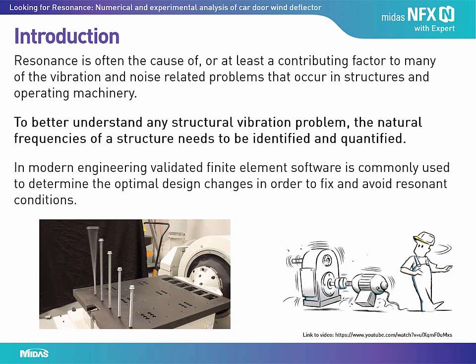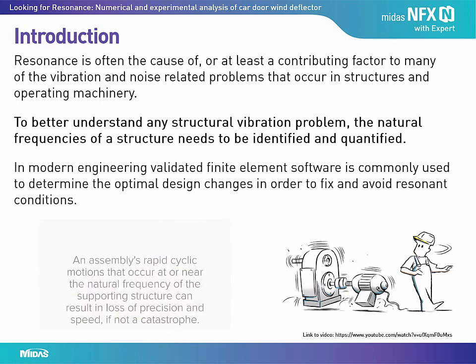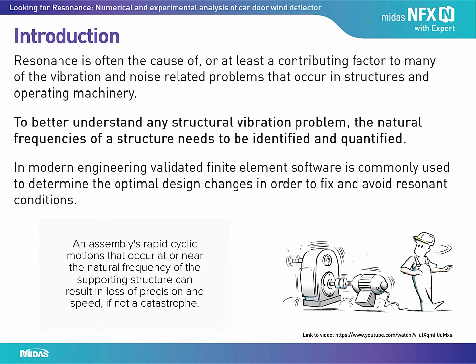Real vibrations are loads which are a combination of excitations of different frequency values, and those components which are close to resonant frequencies can lead to disaster. So resonance is the cause, or at least a contributing factor, to many of the vibration and noise related problems that can occur in structures, prototypes and other machinery.